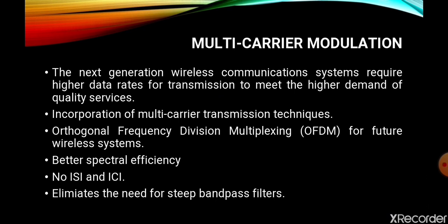The initial development of multi-carrier communication systems was basically done by military systems around the late 1950s and middle of 1960s. These systems are called classical multi-carrier modulation systems, or MCMs, and they transmitted data on non-overlapped band-limited orthogonal signals.